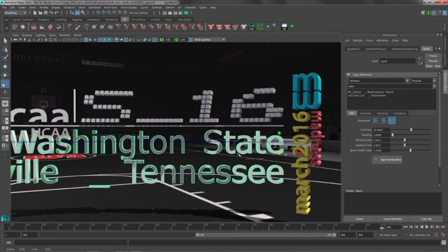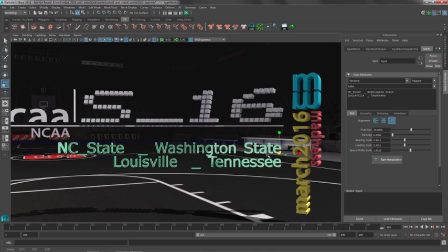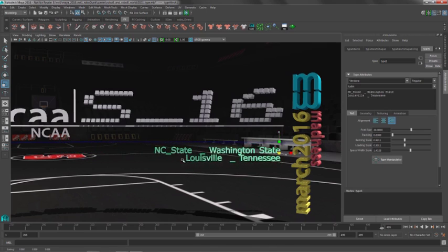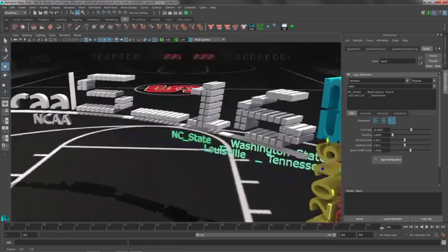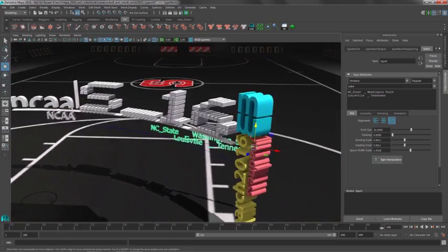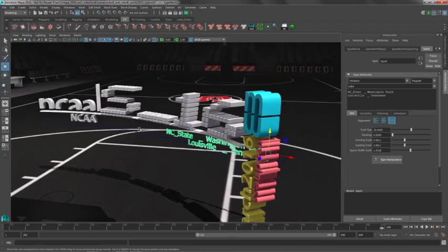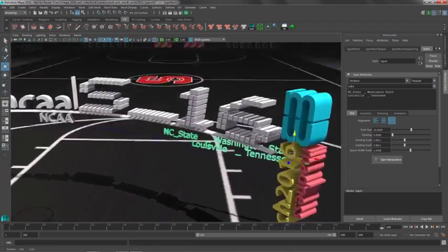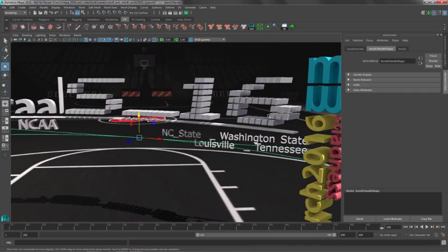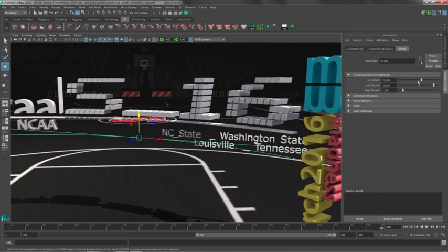So we're going to go ahead and scale this stuff down. And this looks pretty cool. I kind of like it, but you'll notice that it doesn't really have that same arc or bend that this Illustrator file that we brought in earlier using the scalable vector graphics workflow has. And that's because this is being deformed with this bend deformer, this nonlinear deformer.